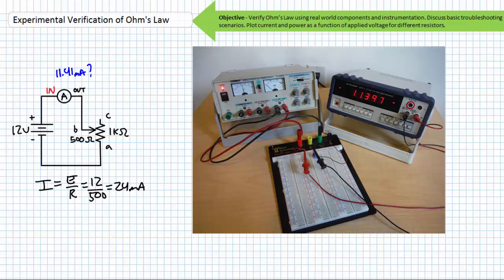I'm using the potentiometer wrong. I'm hooked up A to C and observing all 1 kiloohms of resistance, regardless of the position of the adjustable B terminal. This goes to show you that you could have the perfect voltage and the perfect resistance and still screw it up by building the circuit wrong. Again, Ohm's law quickly and easily and directly routes me to the source of this problem.